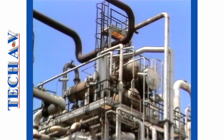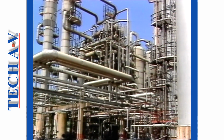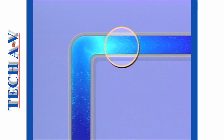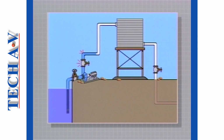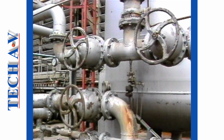In practice, the head potential of any pump is affected by several factors, one of which is friction. Friction always occurs in a pumping system. Fluid particles rub against each other and against the pipe walls. Obviously, the smoother the pipe, the less the friction. Further friction, or resistance to flow, is encountered at every pipe bend and through every valve. Engineers have ways of calculating friction and desired flow rates, but this is outside the scope of this particular program.